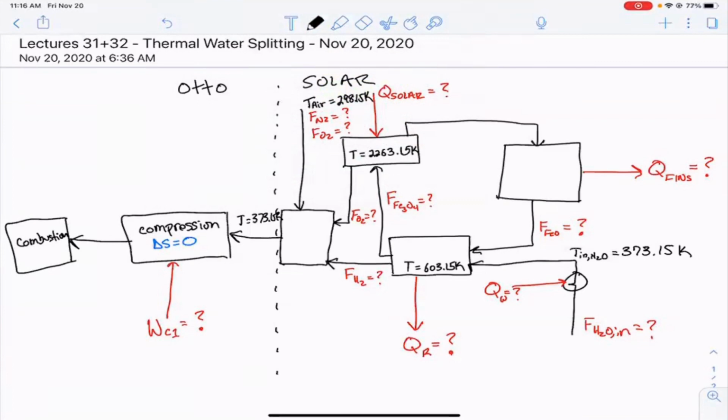So in order for us to figure out the final temperature, a better way to do this is that V in for the compressor over V out for the compressor is equal to 12. And the things that we're going to have to solve for are the same things that we did when we solved for the Otto cycle the last time. We're going to have to find the temperature and the pressure at that intermediate state.